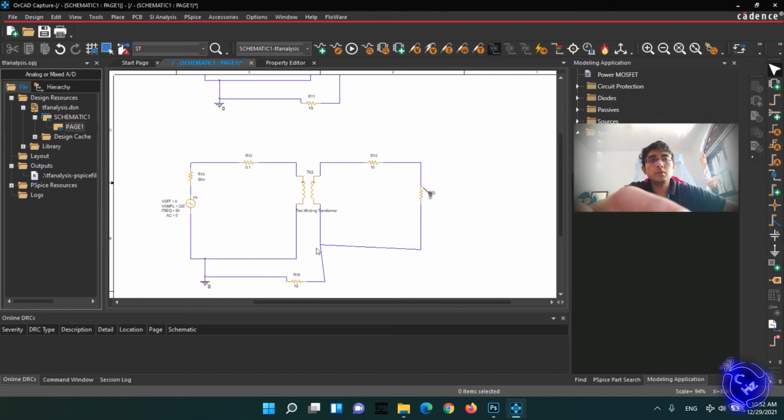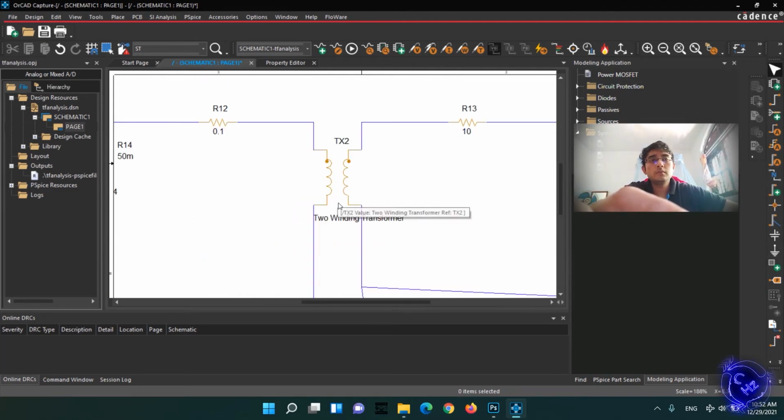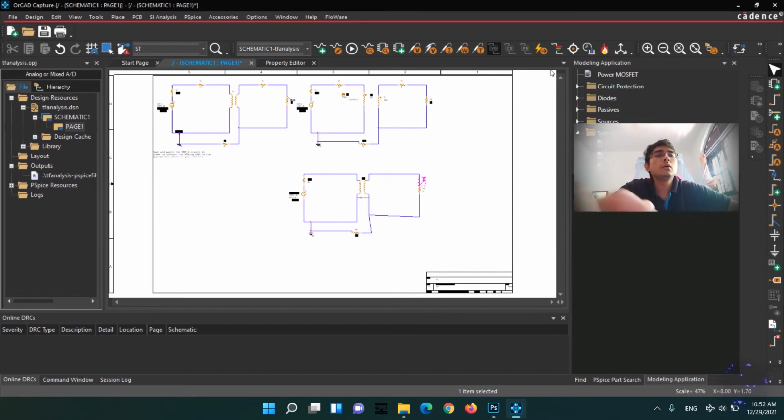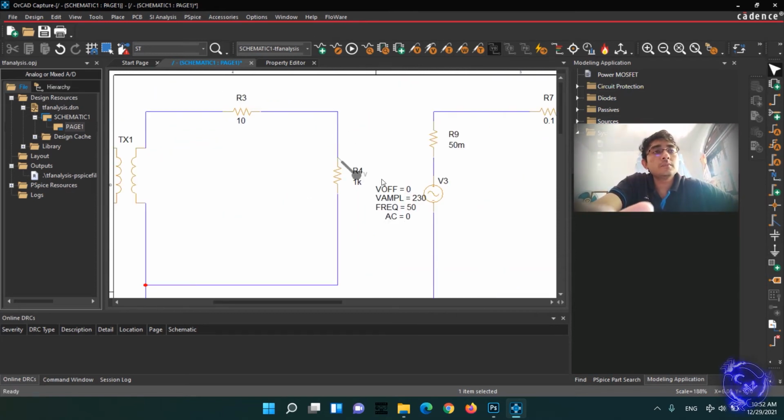And also you have to remember that when I built this transformer, I already gave the primary winding inductance parameter and the secondary winding inductance parameter to my model. So I should remove these two values because those are inbuilt in this block, and also this one. Now this is my output voltage.